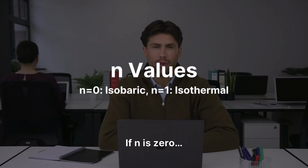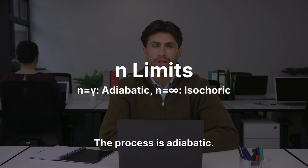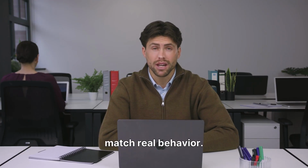If N is 0, the process is isobaric. If N equals 1, the process is isothermal. If N equals gamma, the process is adiabatic. If N becomes very large, the process is isochoric. And if N has any other value, then the process is polytropic. So polytropic process is not fixed, not limited, not strict. It adjusts itself to match real behavior.